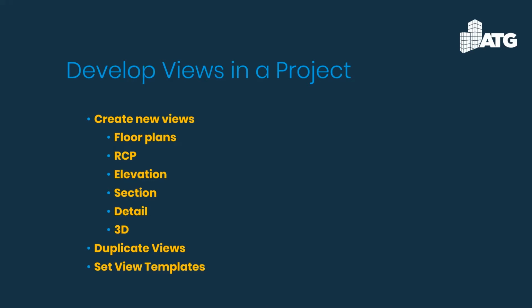And the parent view shows everything within that floor plan. You can do all of your work within there, even go in and do annotations, and it basically cycles down to these dependent views or the child type views. So those are your different options for those duplicate type options.